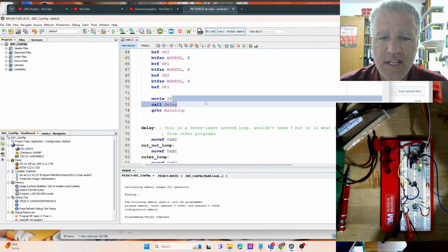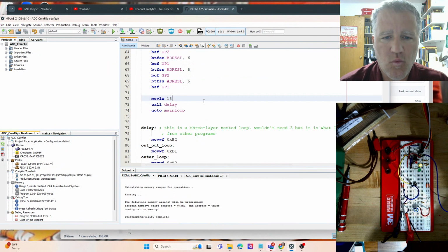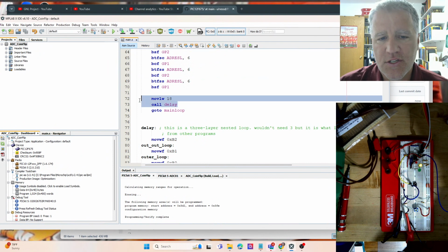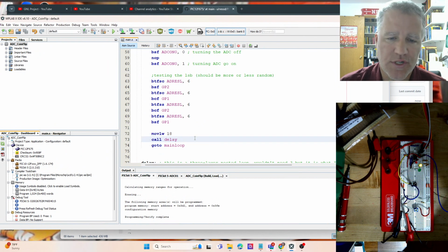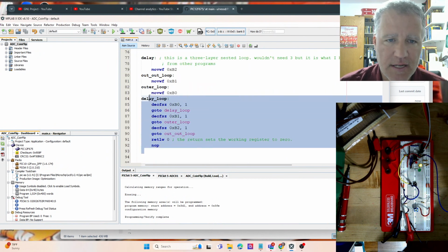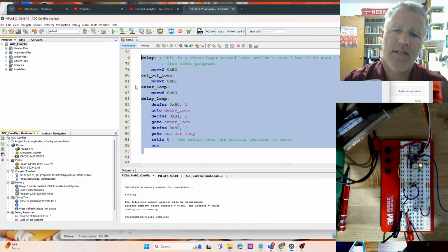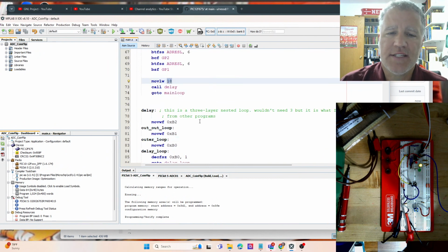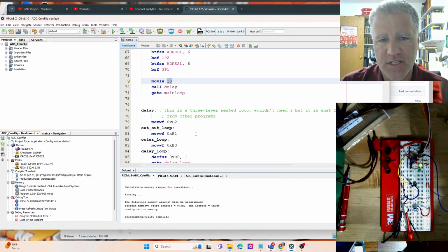Then we have another delay for the loop itself, and I don't exactly know why this is. You have to put some kind of delay in there for the program to work, it seems. It feels like you should just be able to put a couple of no-ops and then it should work, but for some reason it isn't working for me. Anyway, I wanted a delay here anyway, so there's a short delay here. Then the delay loops, I'm not going to talk about these, but it's a 3-layered countdown. So basically, it's 18 cubed clock cycles that it delays for, roughly speaking.